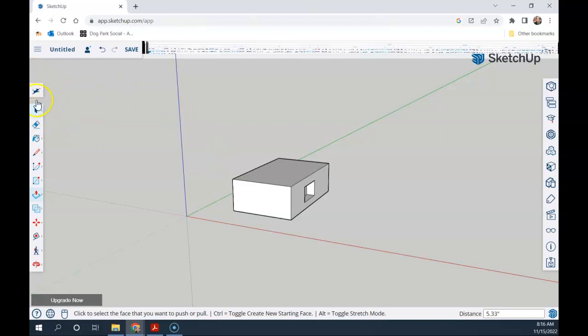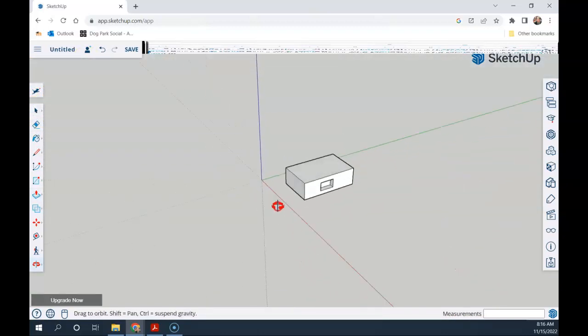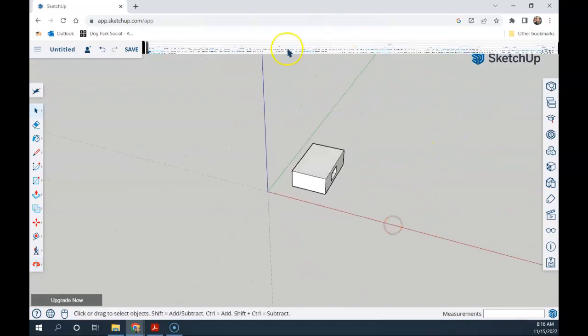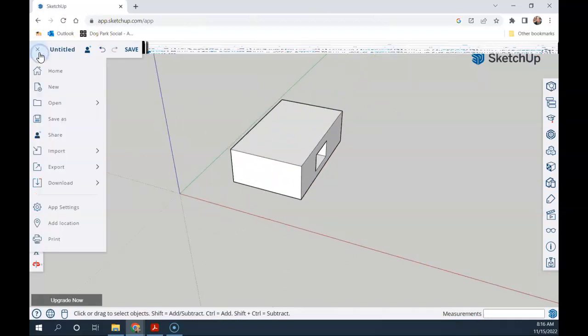So the first thing we have to do is to make sure again that there's nothing else here. When you download your shape, it's going to download everything in SketchUp. So we want to make sure that only the thing that we want to print is here on our page. And then we're going to go down here to this download option. And we're going to create what's called an STL, a stereolithograph file. If you hover over top of it, it'll say right there for 3D printing.